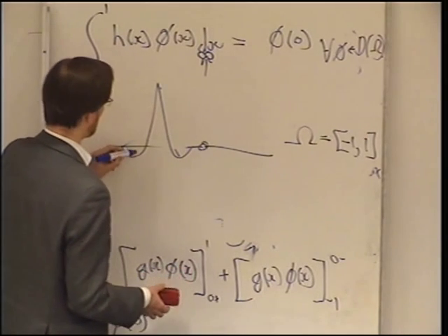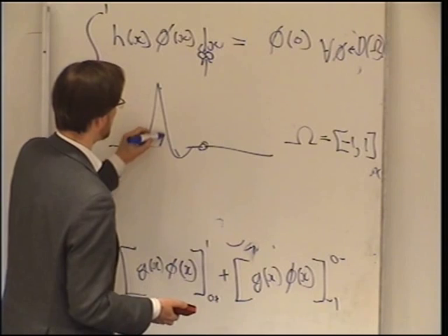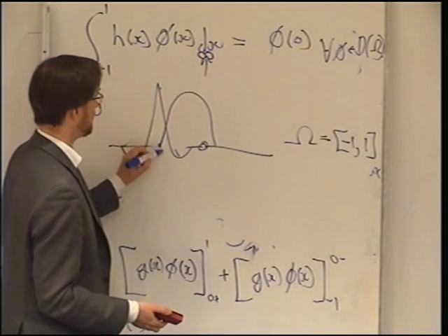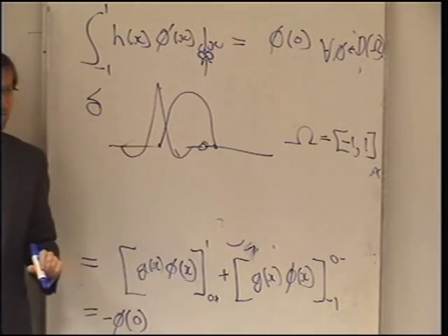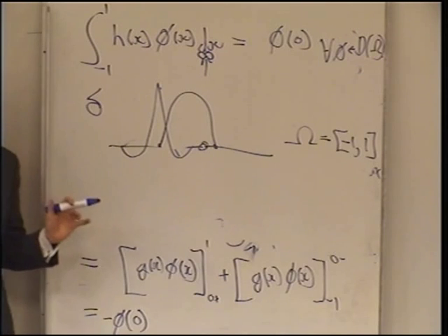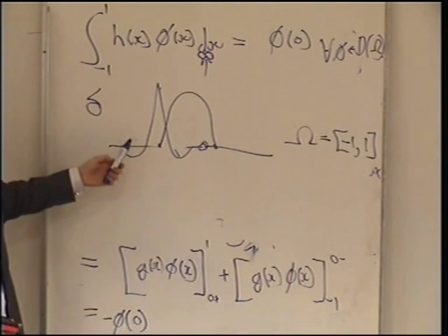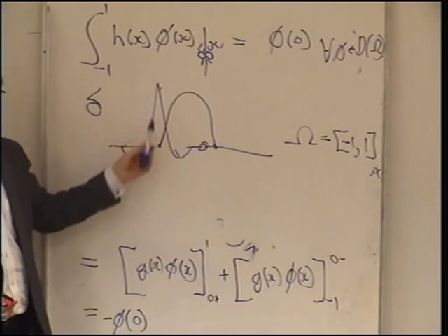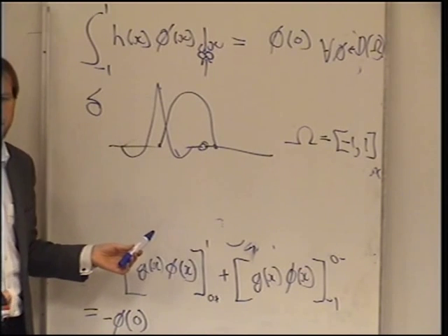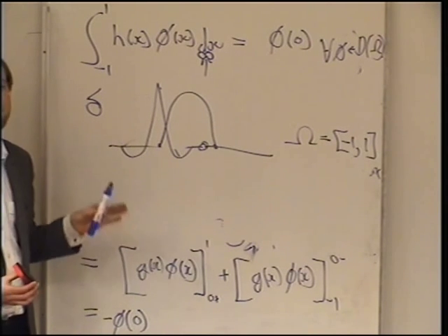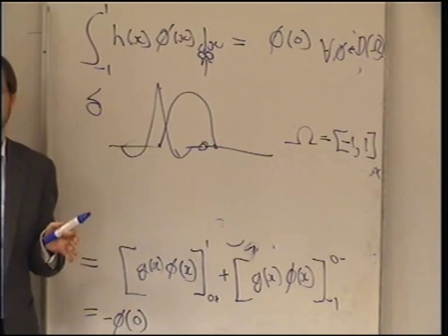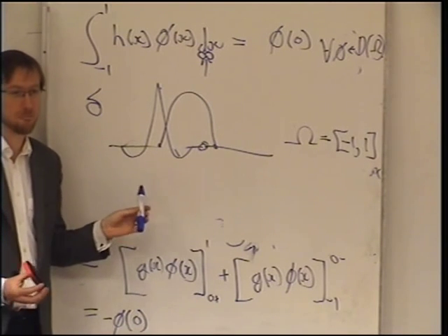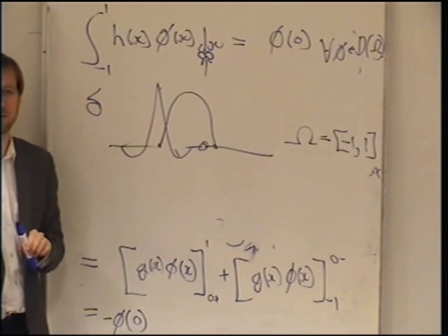And there are other basis functions in that space that look like this, and similarly, they're not differentiable at the endpoints. So even when we have functions which are higher order inside the elements, we typically have them be C0 at the endpoints. But that's all okay. We can take a first derivative in that case. You can't take a second derivative.